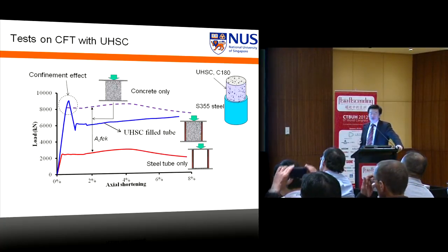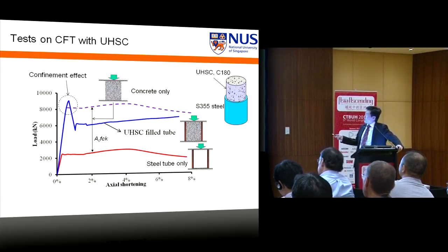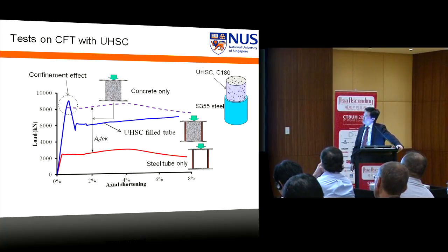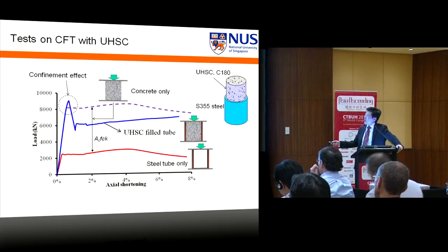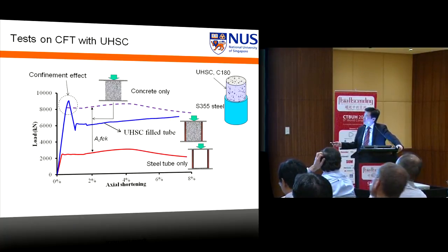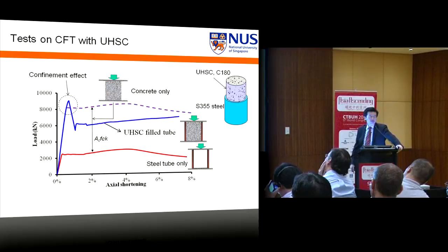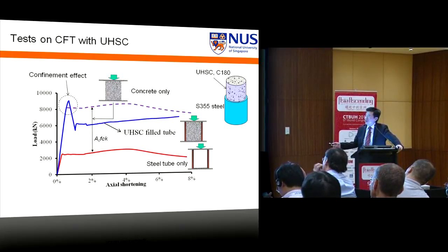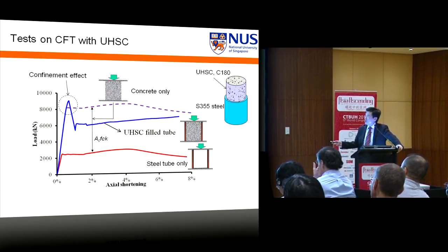Now, once you infill the same tube with the ultra-high-strength concrete, you do that. And this is the concrete that you get if you improve it. Sorry, this is the dashed line you should get. This is the concrete strength, increase over steel strength. But you test the composite tube, you get a peak over here. That surpasses the combination of the two. But for a short while only, you start to unload. Okay, it's called sharp unloading on these composite columns over here.